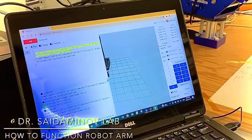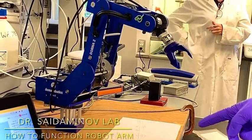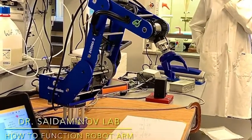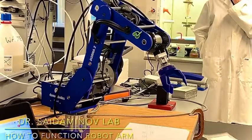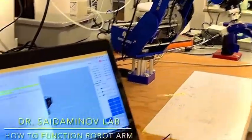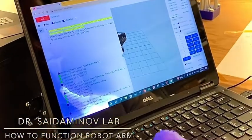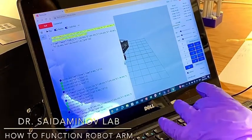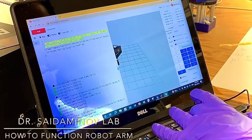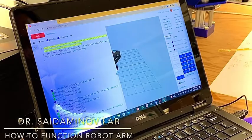So this is the first line that it is going to run. It goes to the first position. Then after that, it's going to go to the second position. But as long as I'm seeing it is going correctly, I can change the velocity to see it quickly. Just a second. Halt. And I can go here, and instead of that, I can put 100, 200, 500. These are velocity, acceleration, and jerk.